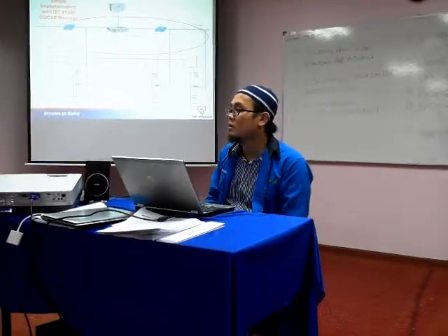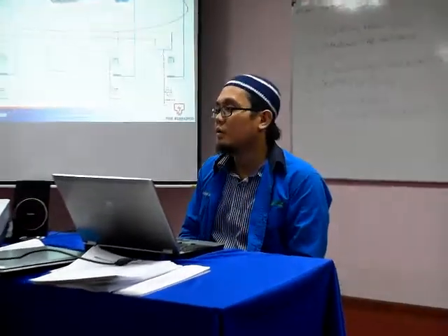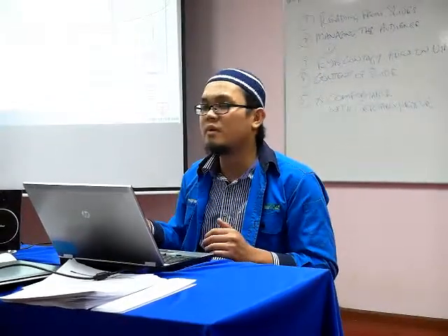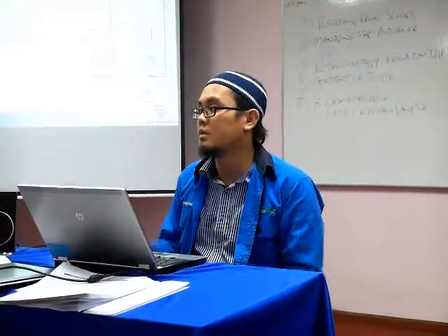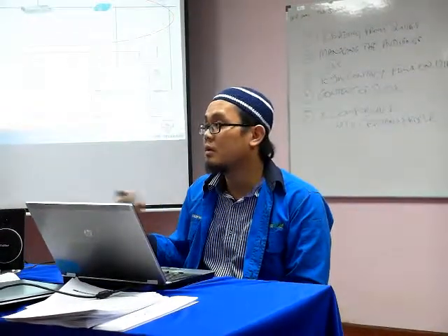Another question, why did you choose only one kV? How about the higher voltage? For my project now, at 11 kV they already have the breaker failure protection scheme. But for 132 kV, only typical substations have breaker failure protection, and on the other substations we didn't have any breaker failure protection scheme installed. For a new substation, it depends on the policy or the scheme used at that substation, because TNB engineering has invented 3 methods.